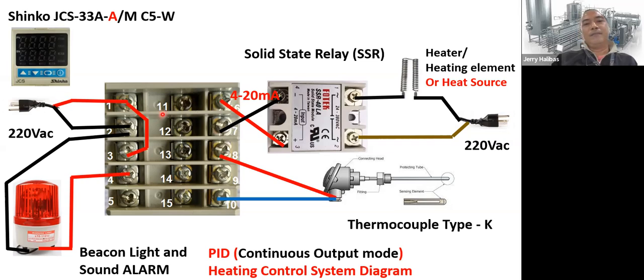The model now is different because its output is a current output, 4 to 20 milliamps. Unlike last time, when it was a voltage output. Since it is 4 to 20, it is continuous, proportional from 4 to 20. It has a linear, or proportional, response.